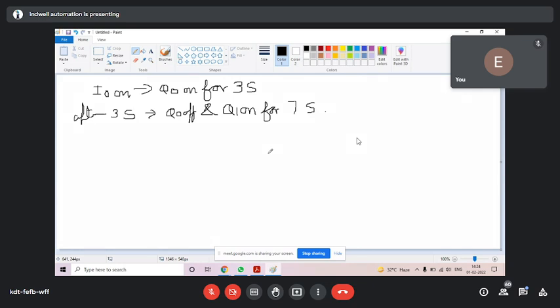Suresh, if you want to terminate the operation in between, then you need one manual signal, like I1 NC, also you will have to use. I1 NC will also break the latch if you want emergency off. For emergency off, I1 will be used. For these programs, we have not been using it. In the next example, I shall give you.